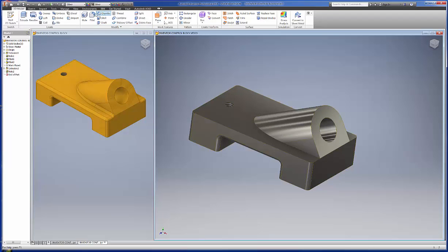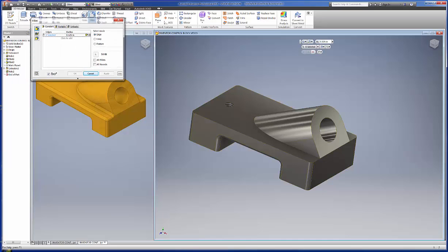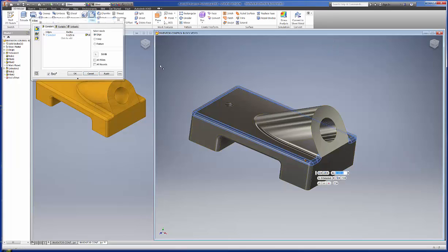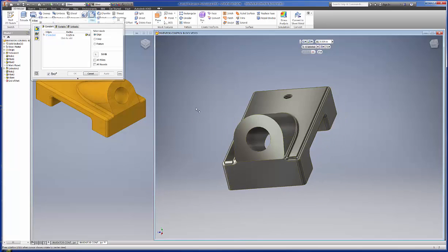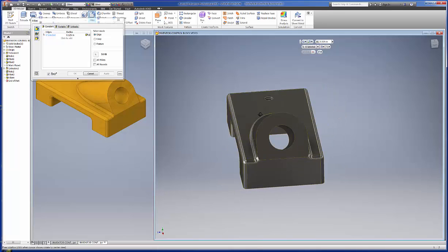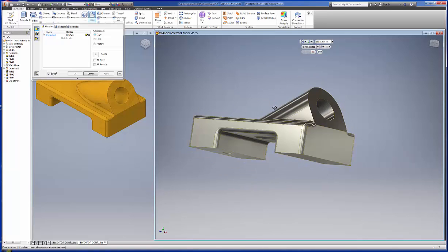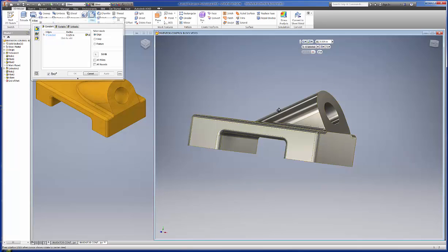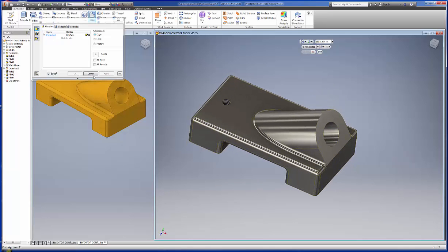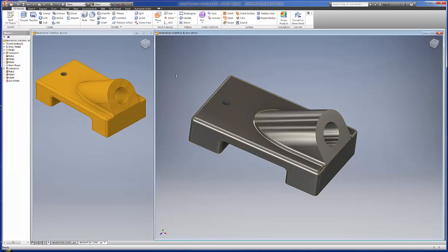Then I'll finish out my fillets. Okay, and it's still set on 1/8 inch. So I'll go around the top edge here. Actually, I want to go around this edge first, I think. Apply that. Then I'll go around the top and apply that. And I think that's it. This edge is actually machined, and the bottom is machined. Of course, you don't fillet the hole because it was cut out as well. So that takes care of it. And that is the control block.